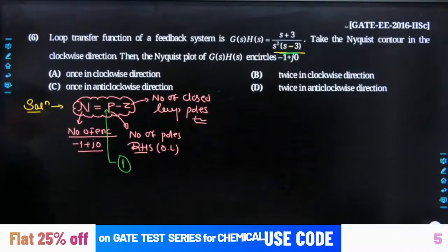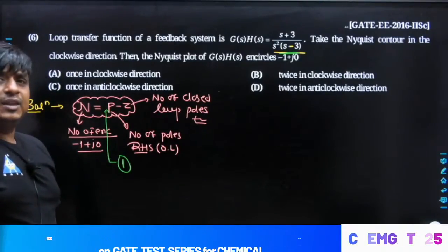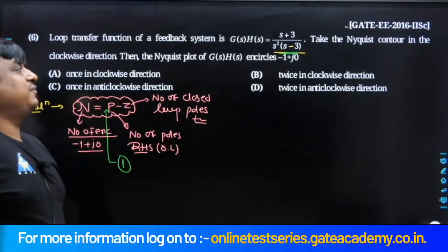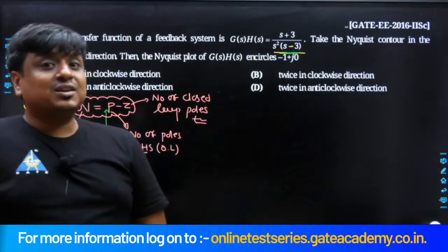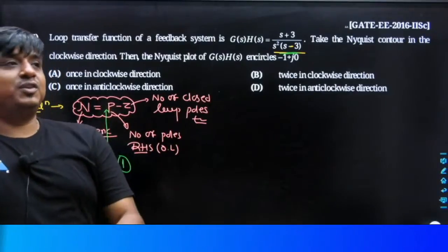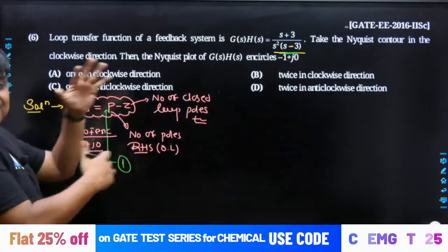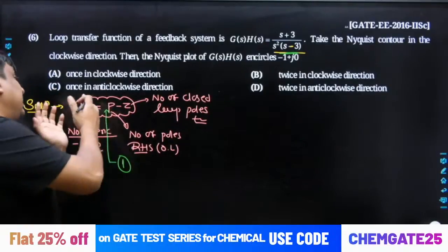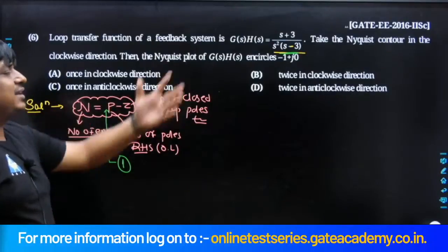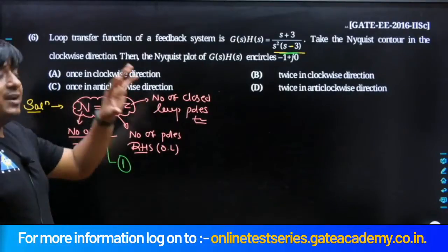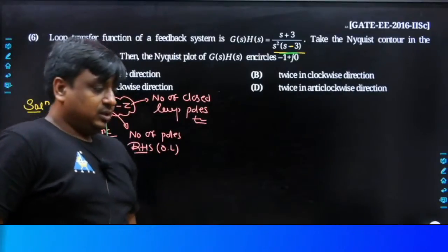And now the person is going to get the number of closed loop poles towards the right hand side with the help of either of the methods we have used earlier. Probably the simplest one is the Routh array. So rather than drawing the polar plot and then the Nyquist plot, and then getting the value of N by focusing on P and Z, because this calculation and its plot would become too difficult. Agreed, no?